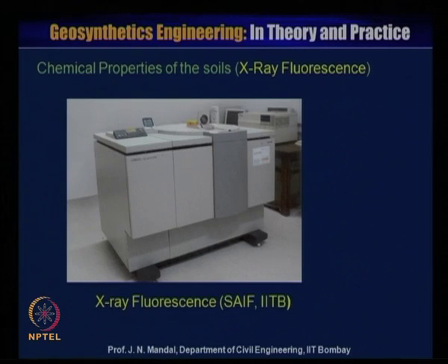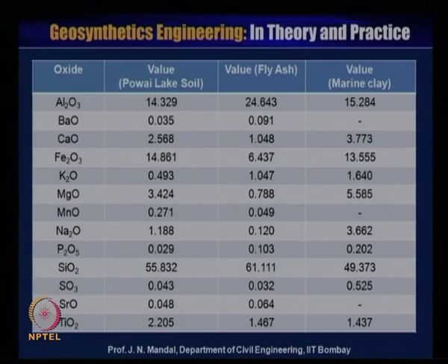Next is the X-ray fluorescence test. This is the equipment that has been used, from SAIF, IIT Bombay, and from this test we can obtain the oxide values for Powai lake soil, fly ash and marine clay. So, Al2O3 for Powai lake 14.329, for fly ash 24.643 and marine clay 15.284.